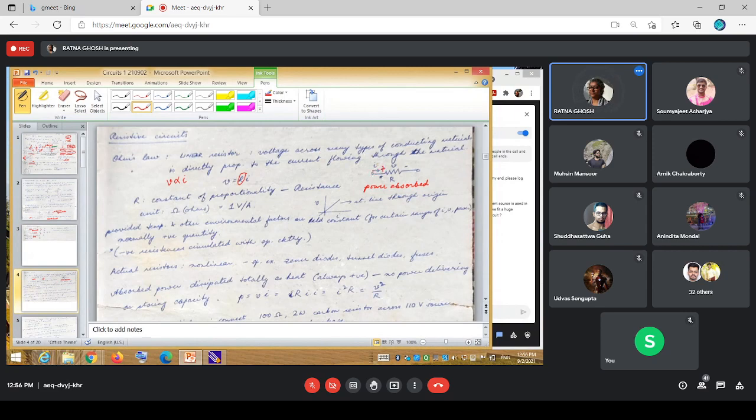Okay, so I in this direction is positive, into this V value, which is positive at this end. So V into I, positive into positive. So power absorbed is V into I. Had this current direction or this value been negative, that would mean the current direction would have been reversed.